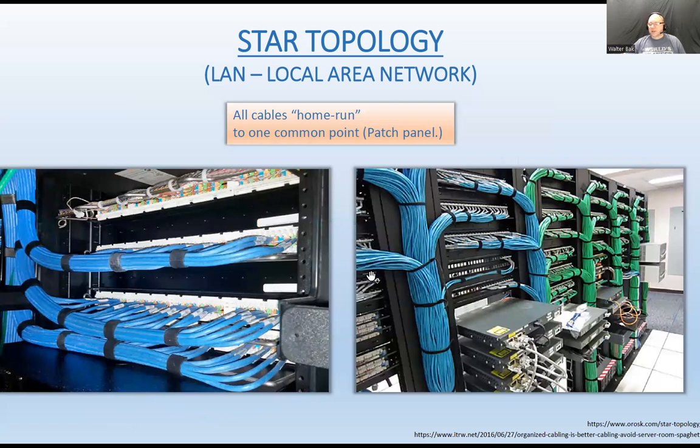Well, installing networks, you just run the cables, you home run them, terminate them, certify or qualify them, give the documentation to the client, take a bunch of pictures, just like we do in our labs deliverables. I'm getting you to practice following the instructions to the T. So they're going to make your life easier once you find the job.